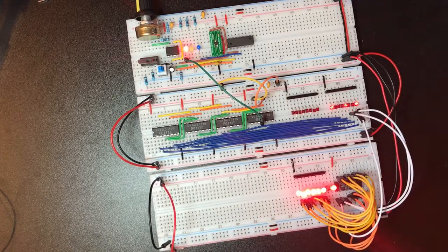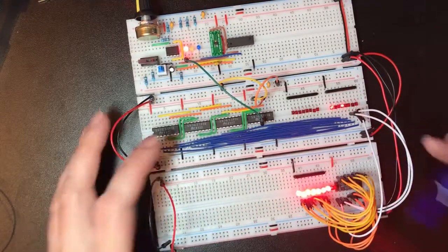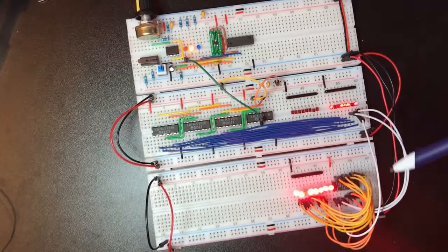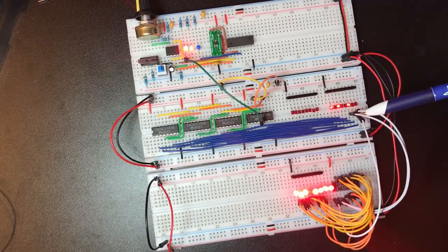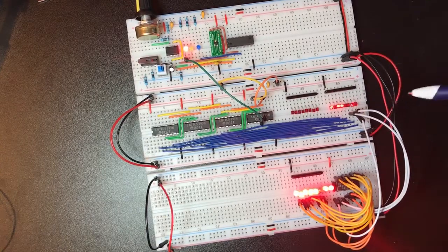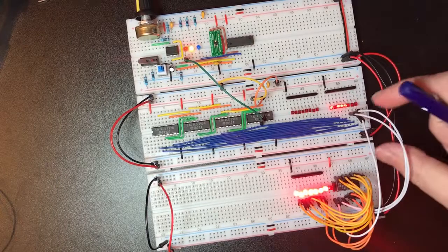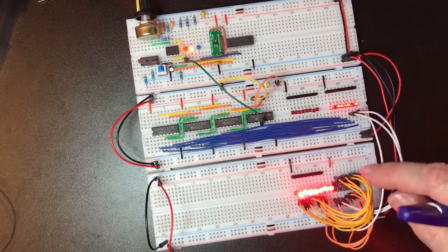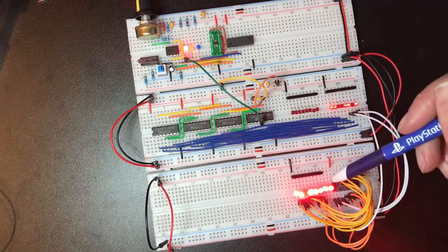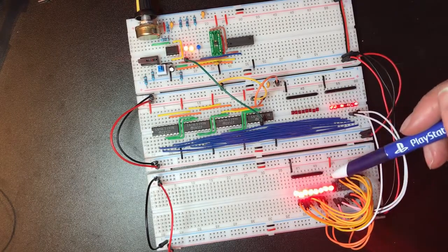So it's quite easy to imagine here how we would have, so these three white wires, instead of being connected into a counting register, would actually go into one of the control units in our processor, and that would output 3 bits of data, and then the register we want can be selected onto the bus.